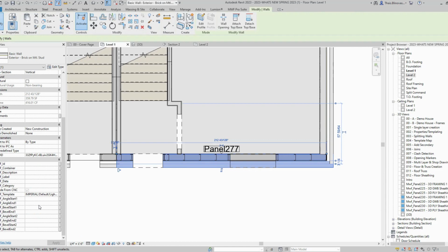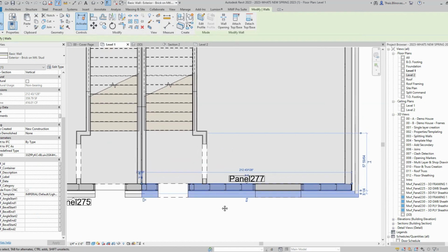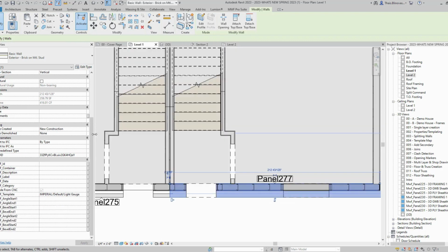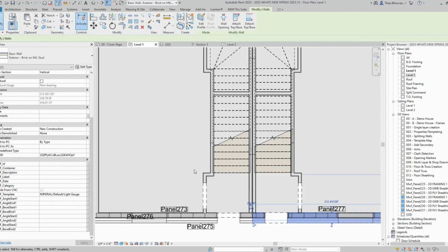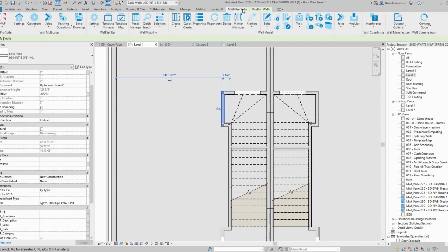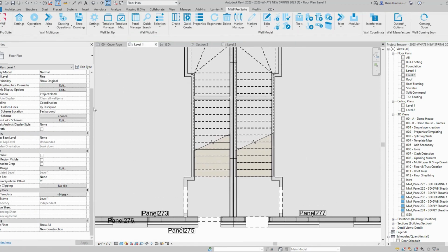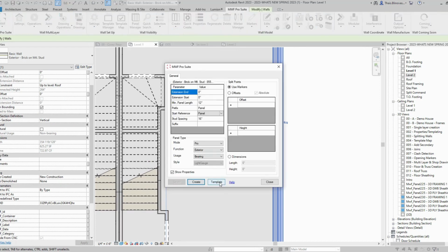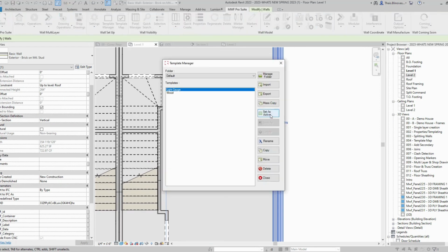And now, one other option that is also very, very helpful is that we now have available a BIMSF template parameter. So before, and this is also valid for standard panels. So let's say, let me select another wall here, just a simple wall. Maybe this one here on the side, this one. So I'm going to go ahead and just create a standard panel.